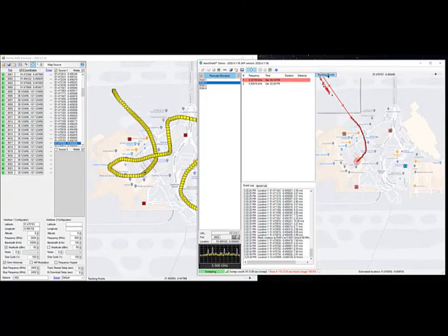You can look at individual plotting points as we see there. So these are different parameters that you can play with to get different modes in terms of the track, in terms of the actual smoothness that you like to see in the path that the drone takes.